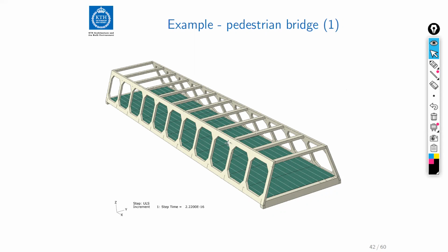This is a sound assumption because people walk with a frequency around 2 Hertz, and even if we try and run our fastest, 5 Hertz is simply too fast. We cannot do that. So any structure that has frequencies above 5 Hertz will be influenced by the overtones of the stepping frequency and not the fundamental frequency of the loading.